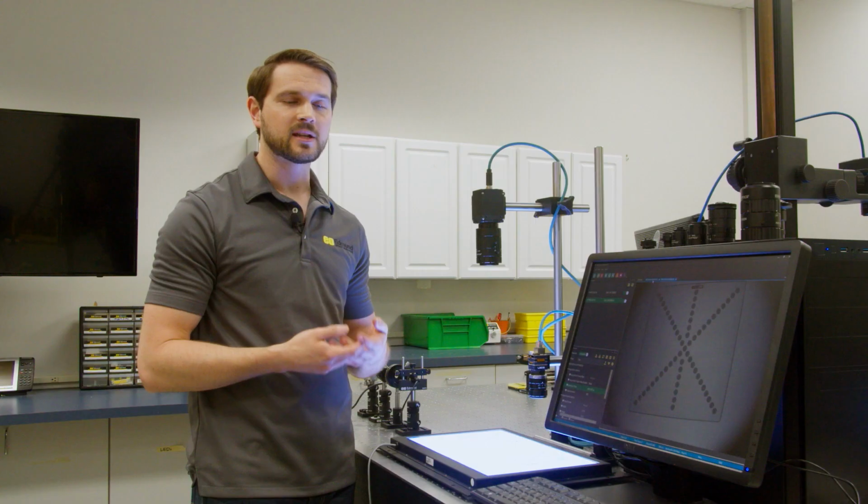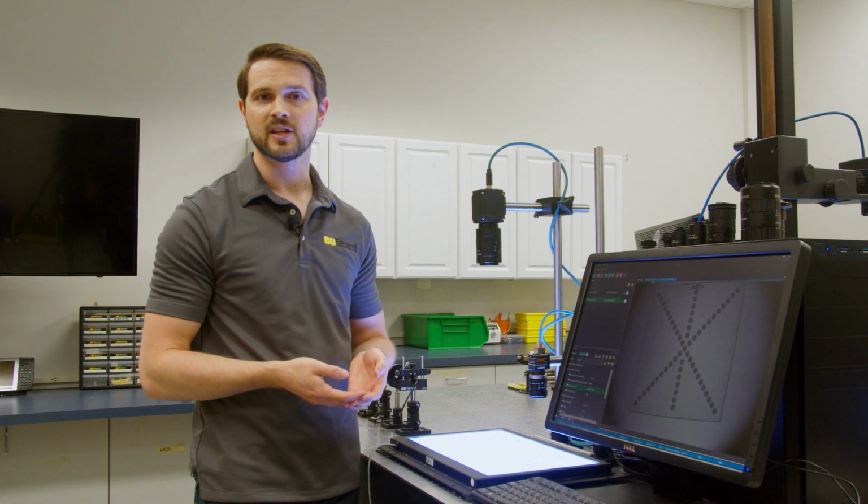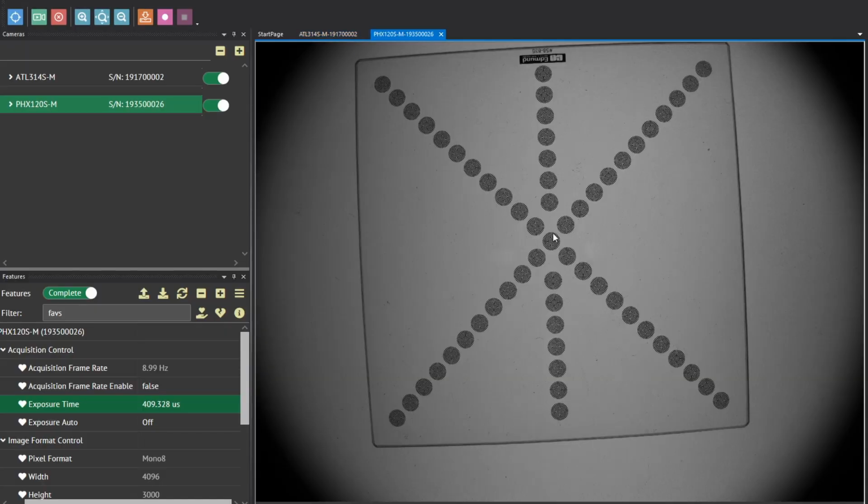And one of the ways that we can dive into detail on that in a lens spec sheet is using what we call a relative illumination curve. The relative illumination curve is going to plot our relative lens brightness from the center of the image all the way out to the corner of the image, which is really saying what's the brightness along a particular image radius, right? Because we have the diagonal, which would correspond to our overall image circle diameter, right? So that radius then, of course, being half that diameter.